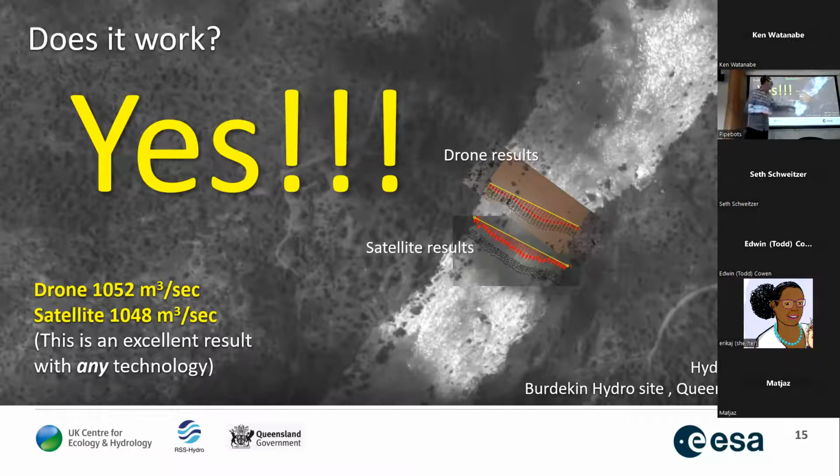So what we've plotted up here, nice and visually, are the velocimetry from the drone and velocimetry from satellite. So you can see a very similar shape. If you could read them, you could see very similar velocities are calculated there. But most importantly, discharge calculated from the drone, 1,052 cubic meters a second. Discharge calculated from the satellite, 1,048. So I mean, you couldn't get a cigarette paper between the two. So that's an excellent result with any technology. So for a first go using imagery shot from space, we were pretty much blown away.